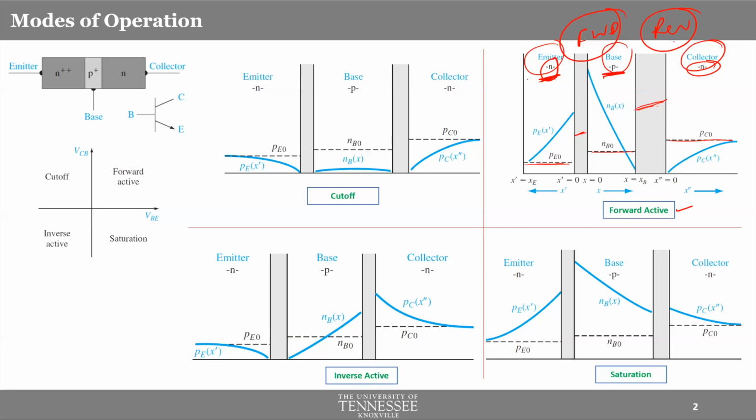In any type of semiconductor, you have electrons and holes, but depending on the type, you have one or the other as the dominant species, right? One of the types of carriers will be the majority carrier. So for N, we have electrons. For P, we have holes as majority carrier. But in this particular figure, what we are looking at is not majority carrier concentration. We are looking at minority carrier concentration. So in the N-type material, you will still have some level of holes available.